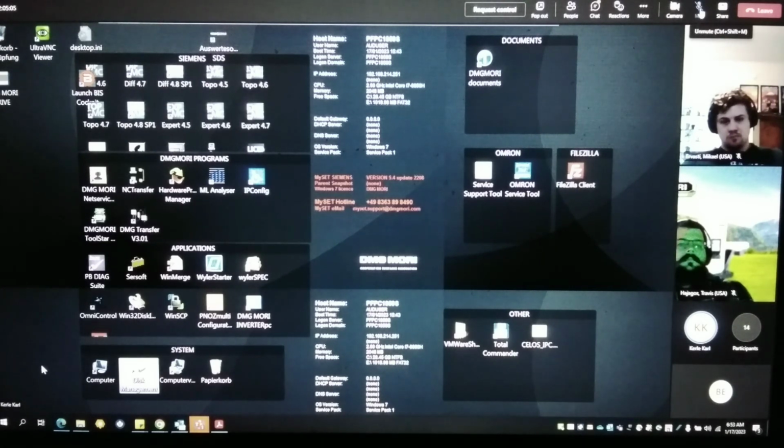We have to install once a linuxbase.img file. That's the preparation for an NCU boot stick. And in the second case, we have to write a ghost image to an empty stick to make it bootable for an IPC unit. Okay? Independent of the procedure we have to do, the main thing first is always we have to check whether there is still a boot partition, yes or no, on the memory surface.